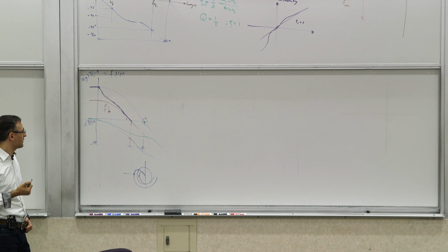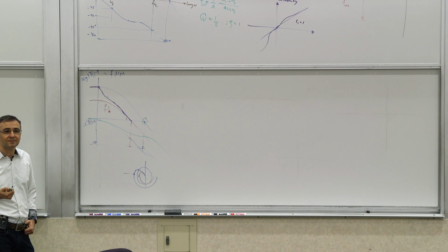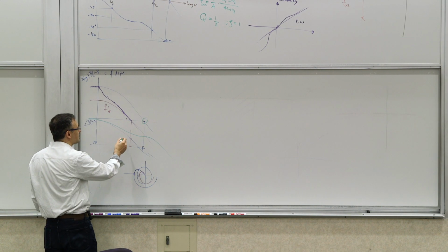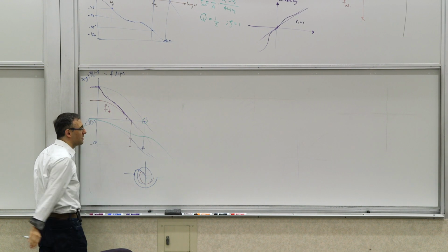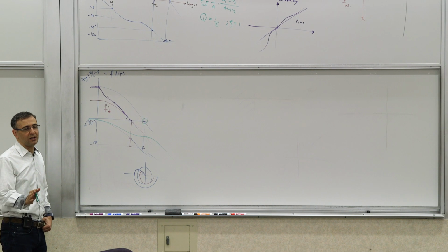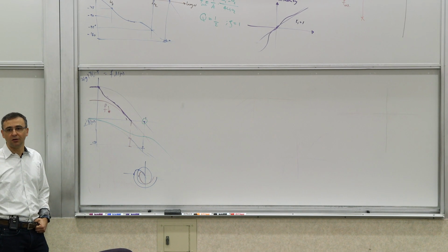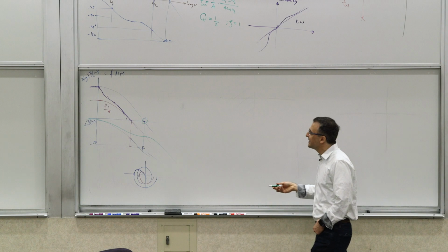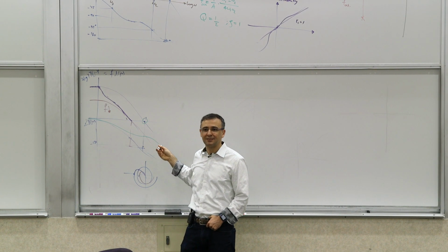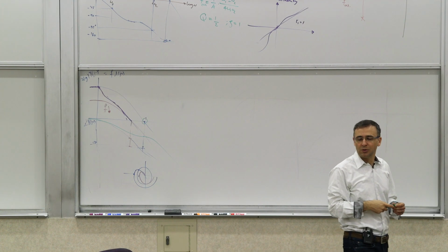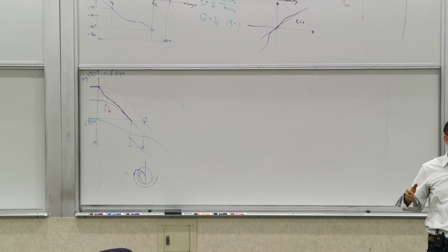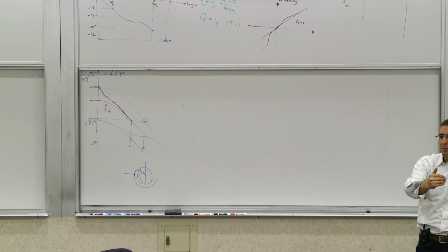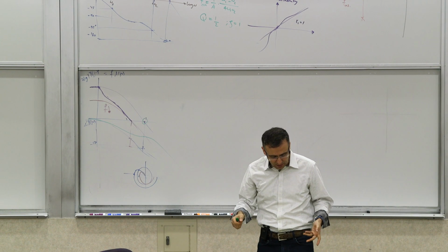A zero, exactly. It has to be a left half plane zero, exactly, very good. If you can introduce some sort of left half plane zero here, then it's fine. Usually, in circuits, if you want to introduce a new zero, you usually introduce a new pole. So you need to produce a zero that happens here and a pole that happens later when it doesn't matter as much. But you have to remember that poles and zeros have a bit of a long reach in terms of their phase, right? It's a decade below to a decade above.